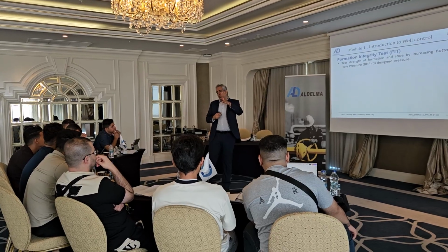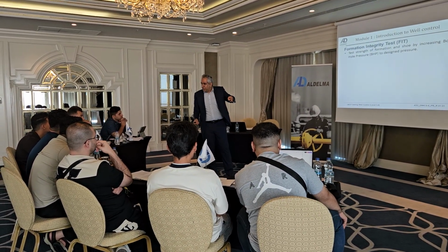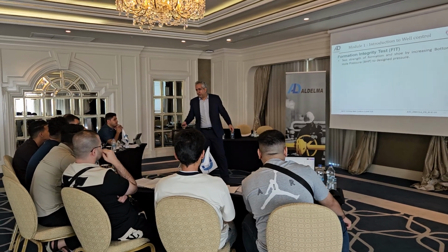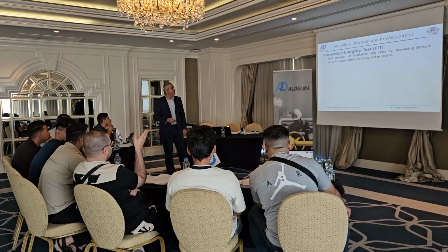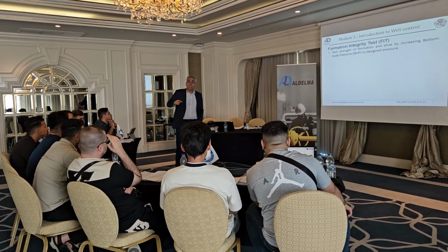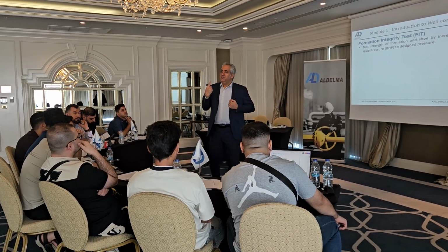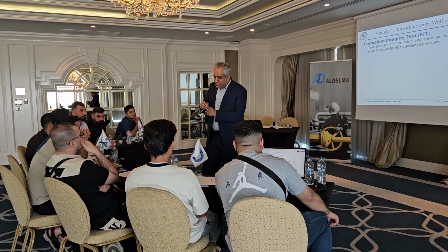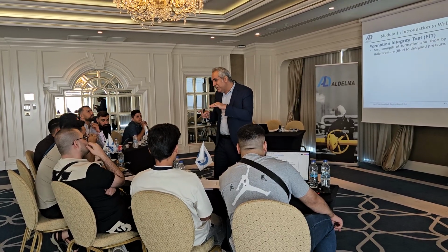First, we check the shoe. Okay, we're going to increase from 10 to 12 ppg. With the 12 ppg, will you hold the pressure or not? Ensure that formation holds. Mohammed: Yes, can we get this information from a leak-off test? Leak-off test, for sure. When we have a leak-off test, we already have the FIT. Because with the FIT, we just want to increase the pressure for the next section.